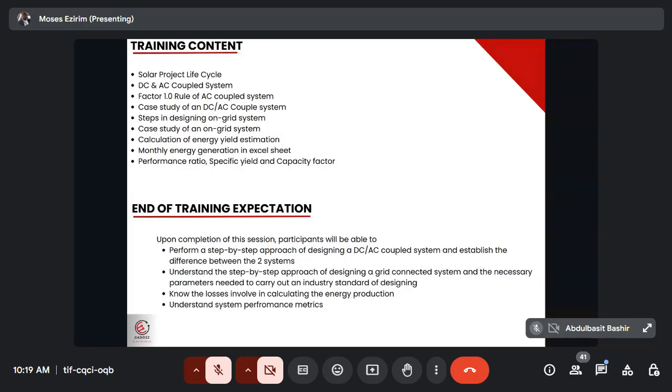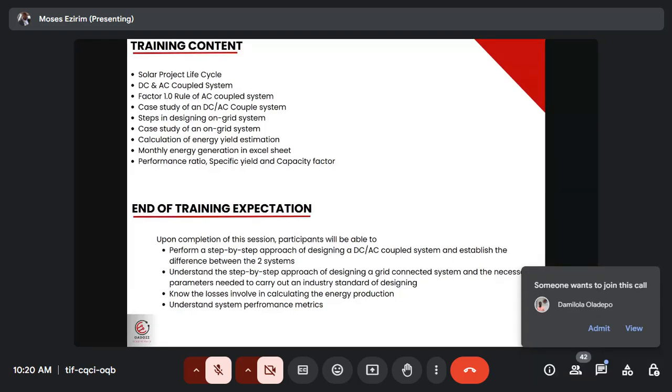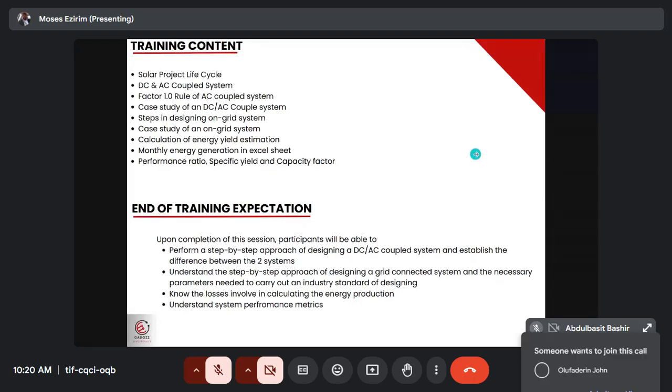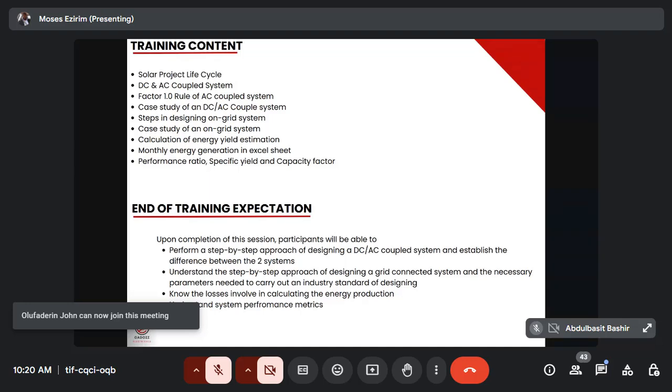Detailed design means what you are going to implement at the site. So the SLD, the AutoCAD design I showed you, is a detailed design. You have to factor in how you are going to bring in your equipment, how it's going to be in real life. There are a lot of things involved in detailed design. Then once you are done with detailed design, you begin your project execution. Execution is the project aspect: you move to the site with the project technician, you start laying your panels, stringing, doing commissioning, and the rest.